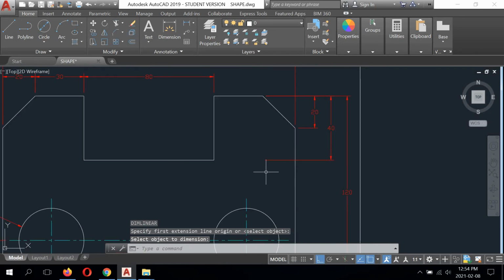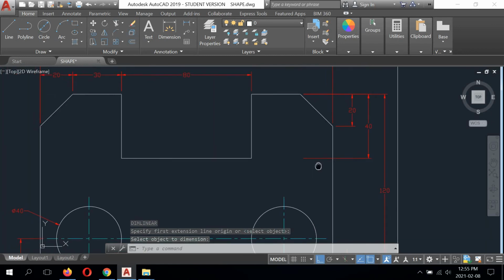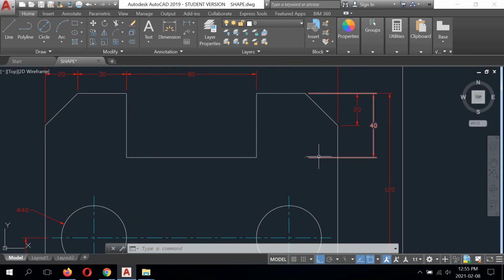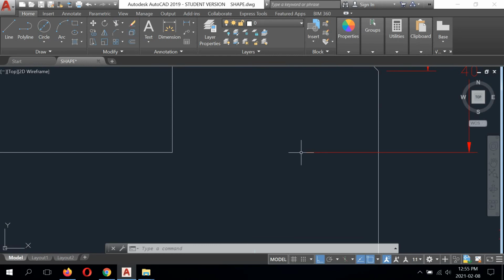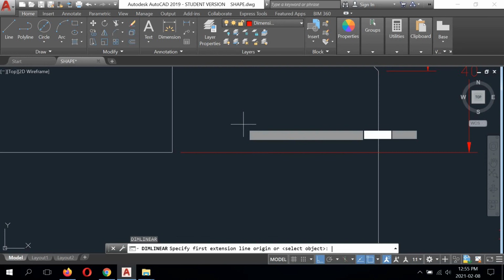This is incorrect because this extension line has to actually travel to the feature that it's connected to. So if I zoom in on this, you'll see there's like a little space here and a little dot. So I can select that and I can drag that grip over to here, and now that's correct.